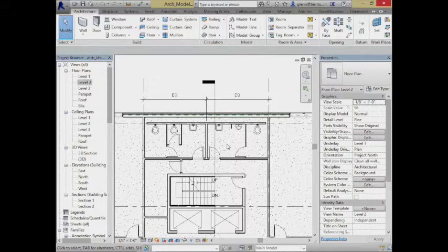There's not so much that it cuts away meaningful structure. So we tend to do that just right within the wall. In commercial spaces, though, we often need a little bit more space. We'll have bigger pipes, we'll have more of them. If I have a whole series of toilets all ganged together, the wall-hung toilets will have a big drain pipe